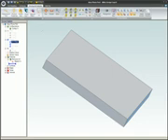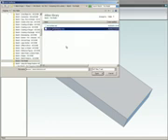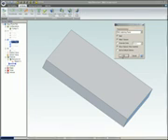In this example, a cell phone blank SAT file is imported to assist in the design of an injection mold for the phone. When the SAT file is imported, Stitch Adjoining Faces is used for face processing, so all the faces on the SAT part will act as a single face. The Heal option is checked to recalculate any inaccurate geometry. The Make Tolerant option will tag inaccurate geometry to assist in subsequent operations after import. These two options essentially act as safety precautions.